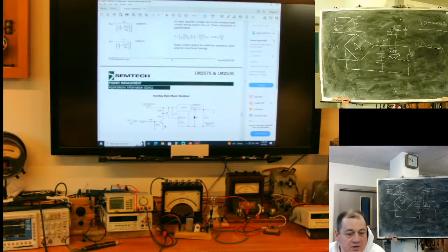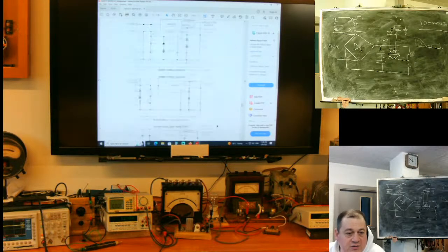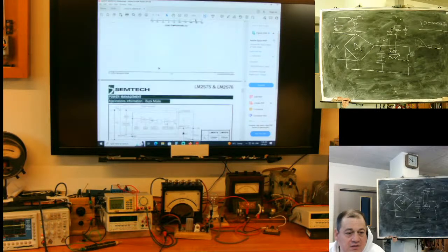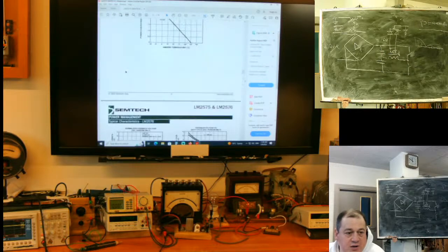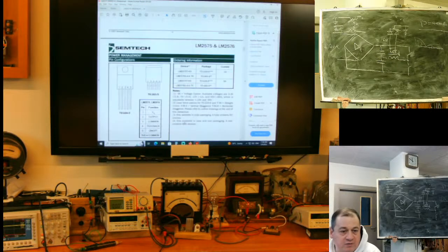It can act as an inverter if you need shutdown. So internal, where is internal? Yeah. Here is the internal logic of this converter: reference point, feedback voltage, PWM current, the shutdown, overcurrent protection, and it has the ability for external on-off control.